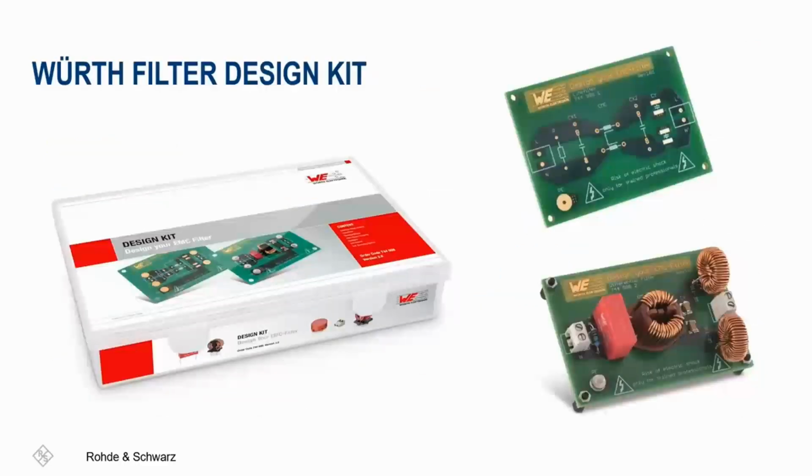Würth Elektronik also offers a specialized filter design kit. It is a wonderful resource for testing the effectiveness of various filters. This kit includes X and Y capacitors, as well as common mode chokes of different sizes and materials to tackle different frequency responses. It enables us to easily swap out components and determine which filter works best. Another reason why we did the experiment with common mode chokes is that the filter board typically requires soldering components in place, making it more convenient to use sockets for capacitors, but for the common mode chokes, it will be much more difficult.